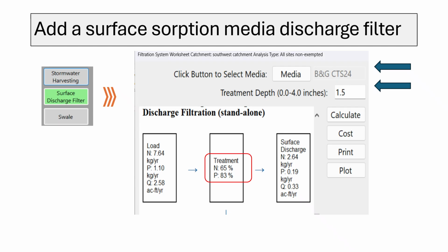total phosphorus. A key operational requirement for this particular filter type is the presence of an upstream storage pond to ensure a sufficient head for proper operation. Fortunately, our existing wet pond can effectively serve this storage need. However, it's important to note that even with the wet pond fulfilling the storage requirement, this option alone does not meet our overall net improvement target for total nitrogen removal, which is set at 77.3%.